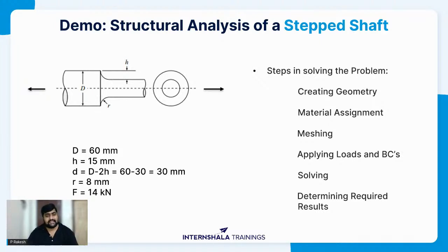The second thing is I also want to find out the stress concentration factor, because if you observe, the cross section on this side and the cross section on this side is different. That means it is changing, so we'll have a stress concentration factor somewhere in this particular region. We are going to perform some hand calculations on the same problem, and likewise perform calculations using Ansys Workbench, and compare both the results as well.